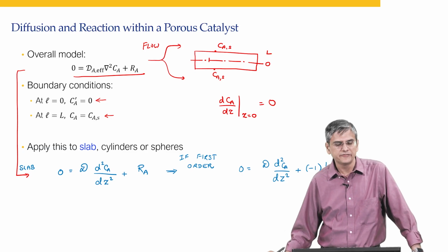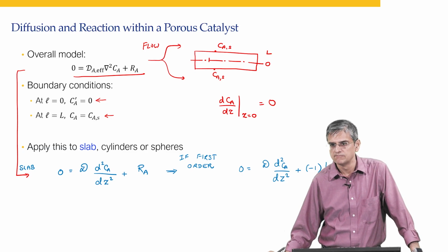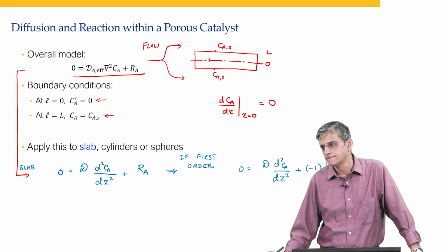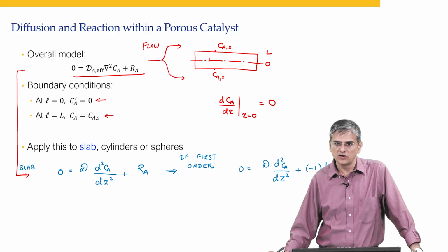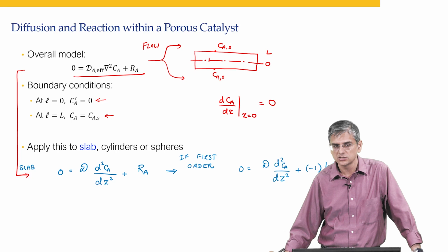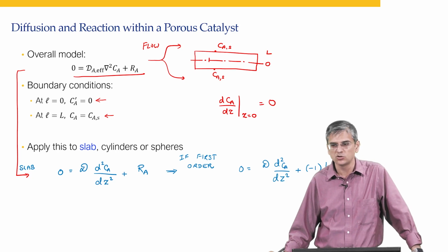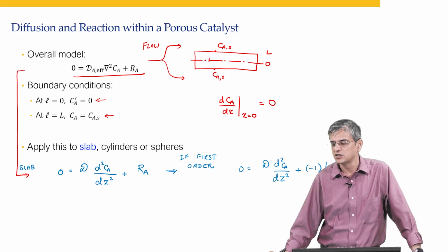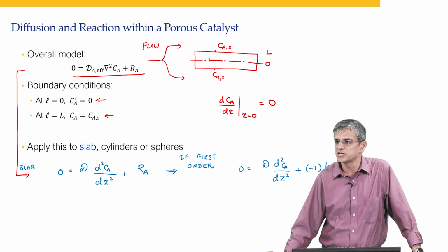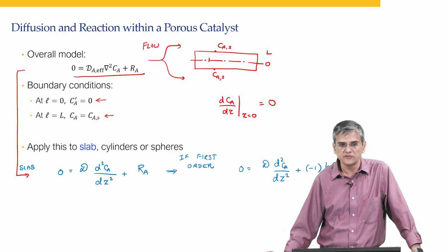You can very well solve it in this form. You do not need to non-dimensionalize it. The advantage of non-dimensionalization is that you can use the concepts irrespective of the size of the particle, and with generalized Thiele modulus irrespective of the shape of the particle also. So that's the advantage of non-dimensionalizing.